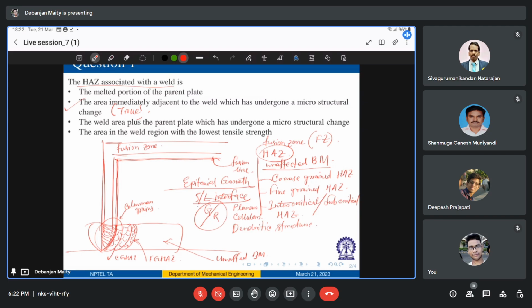So if you see this final weld metal grain structure, it has considerable practical significance, right? It has been shown that a coarse columnar structure is susceptible to hot cracking, whereas a finer grain structure, a distorted columnar structure, or an equiaxed structure is more resistant to hot cracking, right? In addition, the fusion zone grain structure has strong influence on the mechanical properties also.